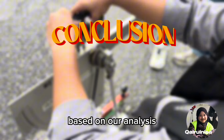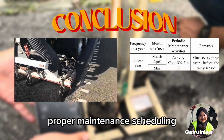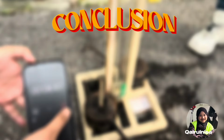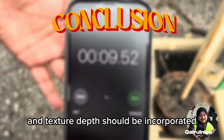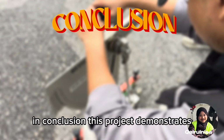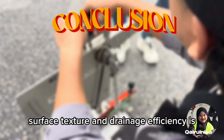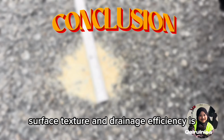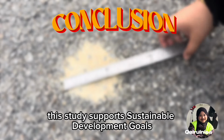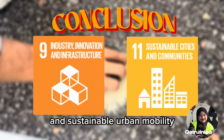Based on our analysis, several improvements are recommended, such as surface retexturing, proper maintenance scheduling, and enhanced drainage design, particularly in high traffic areas. Regular monitoring of skid resistance and texture depth should be incorporated into pavement maintenance practices. In conclusion, this project demonstrates that effective integration of skid resistance, surface texture, and drainage efficiency is essential for safer and more sustainable road infrastructure. This study supports Sustainable Development Goals 9 and 11, promoting resilient infrastructure and sustainable urban mobility.